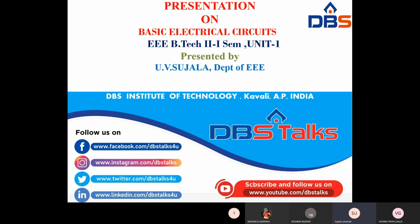Whatever voltage sources are there, we do not change their polarity, as the polarity is already given. The long line is positive and the short line is negative, as in a battery. For the passive elements, depending upon the direction of the current, we have to assign the polarity.